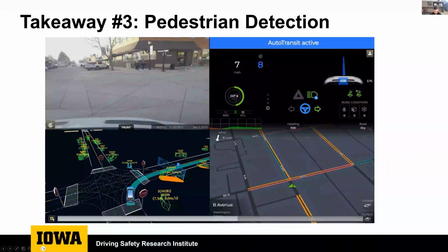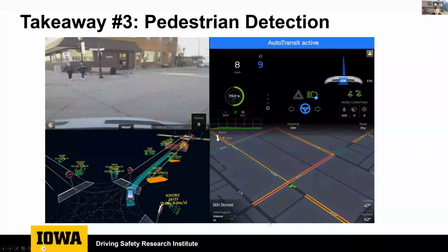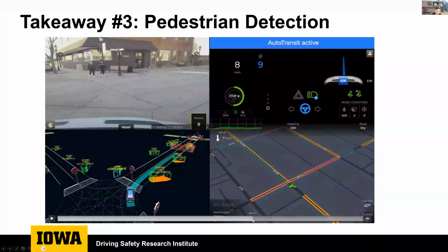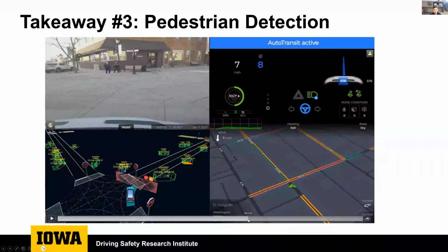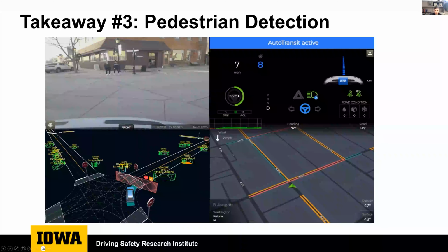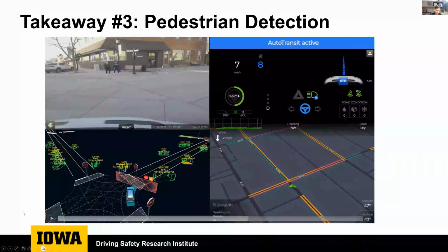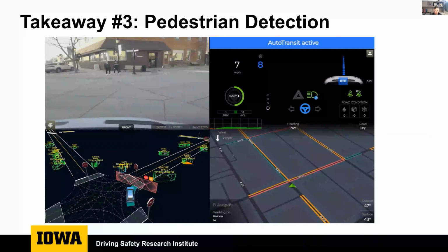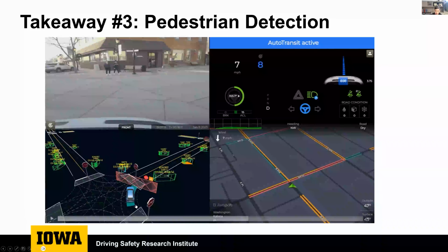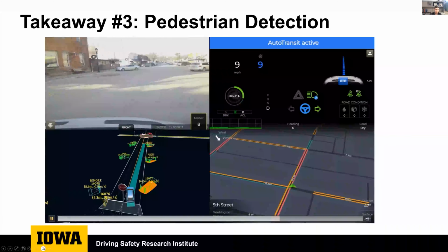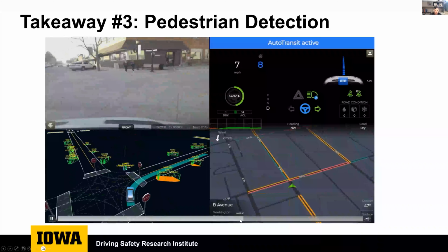So as you'll see, as the video continues on, they continue towards the intersection while the transit continues through the intersection. This can be caused by a number of things, along with the late detection and difficulty categorizing them and their detected plan of travel. That, along with minor latencies in the autonomous software itself, caused a point where even here you can see a frame where the transit thinks it should slow down, but next frame that's gone and nothing actually happens. So you get these times where it did pick them up, it does see them,